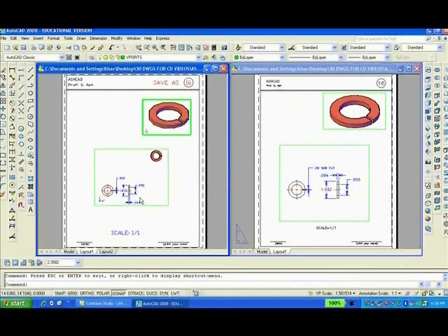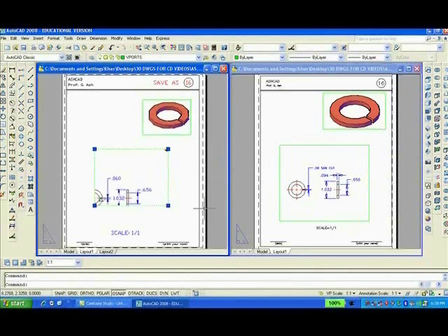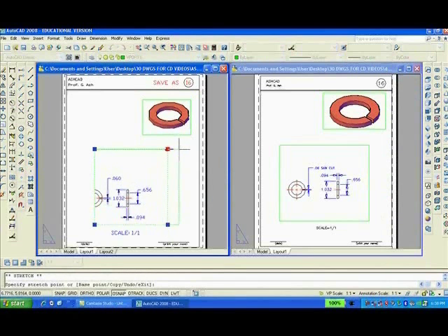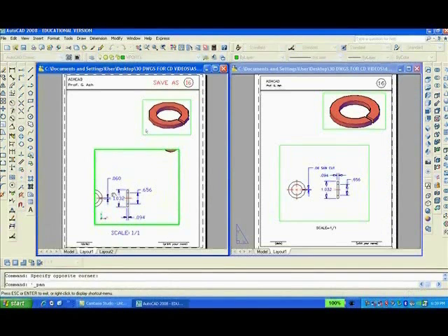and we can click on this, double click outside first, then click on this. That's going to be at 1:1, so we'll go to annotation scale, click on 1:1, made it bigger, which means I'll have to make this bigger, and perhaps even this way. I'll click on that grip and make that bigger. Now I can go inside and I can pan to center it like that.